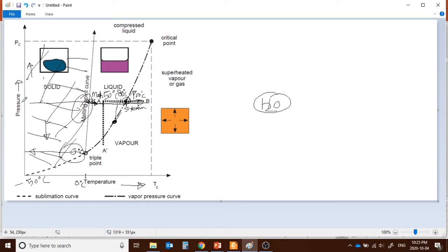So this is, for instance, 1 atmosphere, ATM. Now at this pressure, for instance 0.7 ATM, 0.7 atmospheric pressure, you can boil the water at 80 degrees Celsius. And even if you decrease the pressure more, like at half atmospheric pressure, this being the regular atmospheric pressure we have right now, if you halve it, then what's going to happen? You can even boil the water at 50 degrees Celsius. So this is the phase diagram. That's how it works.